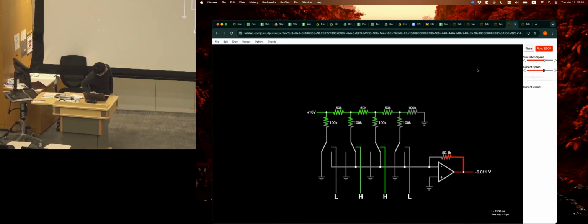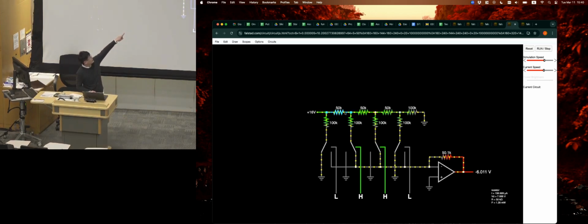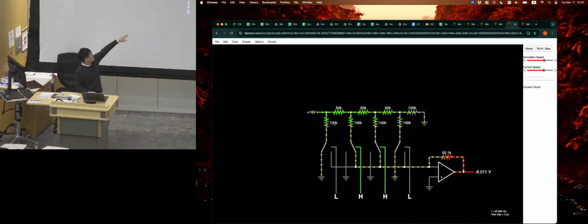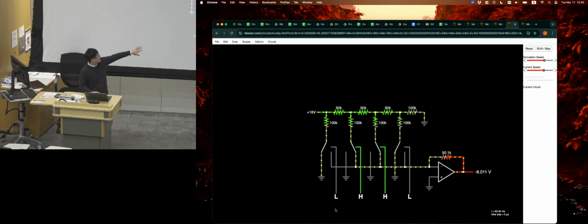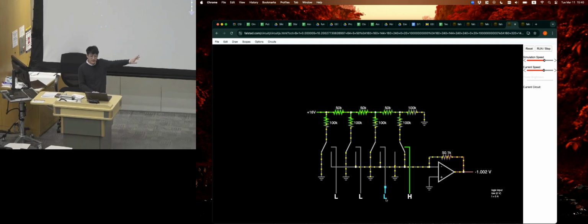So this is what we have. This is the value R, this is 2R, so 50K and 100K. And then you can decide whether you want to turn each one off or on individually. So if everything is low, it's practically 0. Then you start here. You will have 1 step here, and then we have 4 bits, so in total, 16 steps.